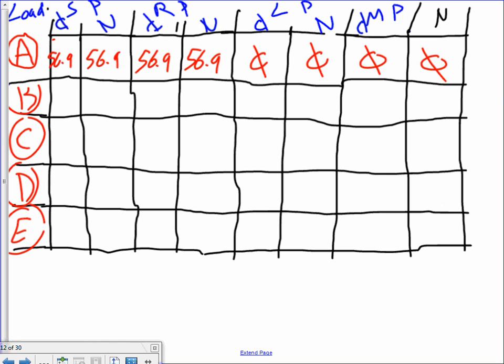One more time, let me repeat myself. We will have a 56.9. These are the receptacle demand load from step A, all the step A that we did, guys. Under the phases, the same value will be for the neutral because all the receptacle loads are connected at 120. They are neutral load. They will be seen by the service panel as well as the receptacle panel. Why do I put zeros for the lighting panel and the mechanical panel? Because they will not be fed from the mechanical panel or the lighting panel. Done. Can I have thumbs up, Chad? We understand why you did what you did. Cool? Okay.